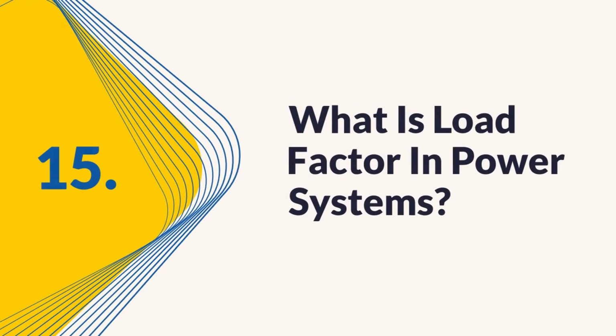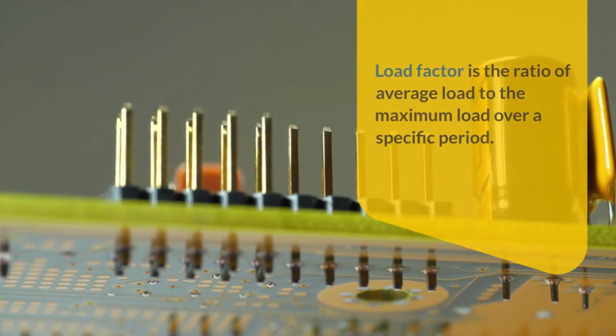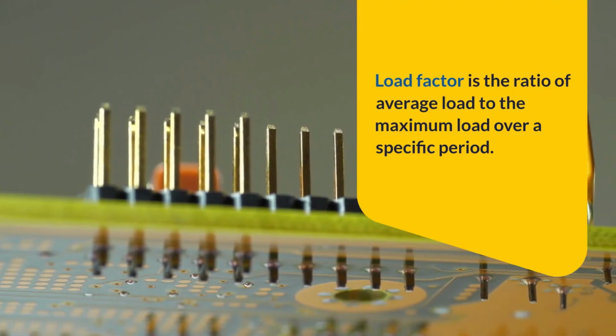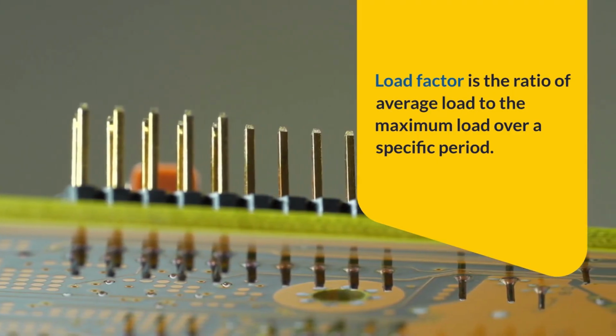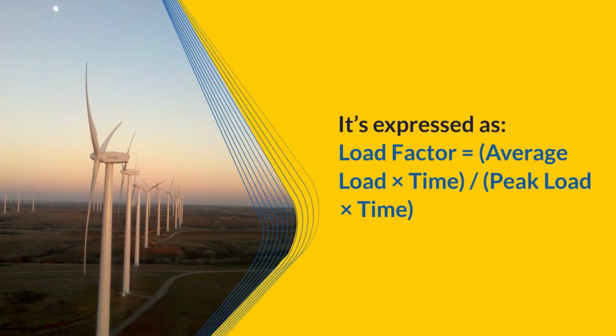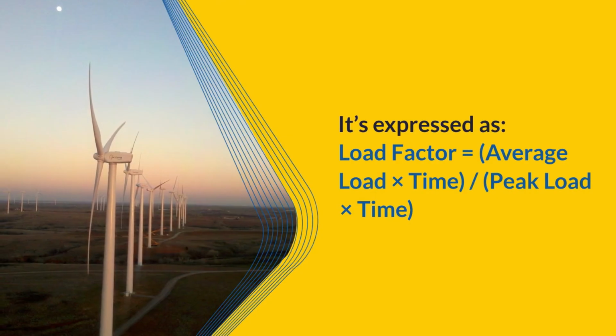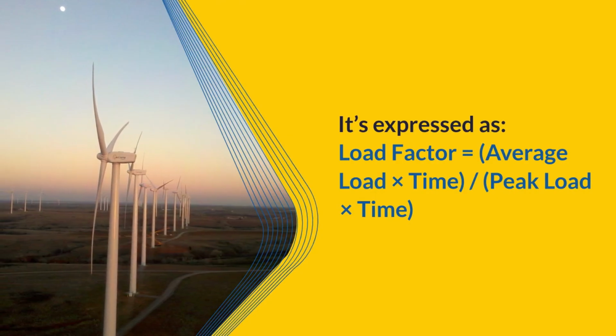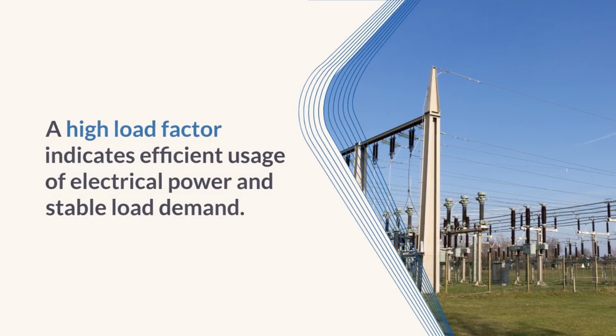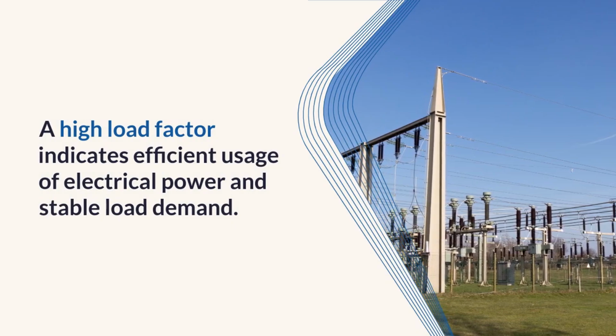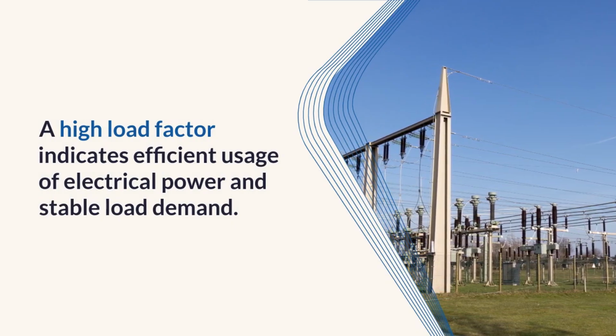15. What is load factor in power systems? Load factor is a ratio of average load to the maximum load over a specific period. It's expressed as load factor equals average load times time / peak load times time. A high load factor indicates efficient usage of electrical power and stable load demand.